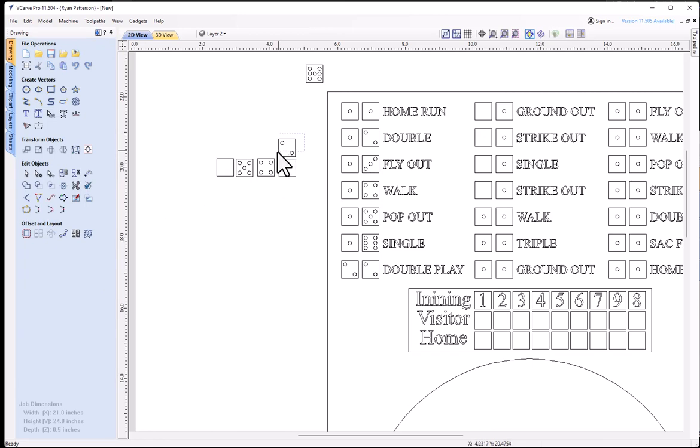Going to look at a different way of pulling those together. So with the letter dice 2, going to use the Control copy as I drag this. So with snapping to the top left, I'll hold the Control key down and snap and make a duplicate copy of each one of these. I can go from center to center. Now what this is doing is creating a vector on top of a vector, which we do not want. So now I'm going to go through and select and delete the duplicate rectangle.